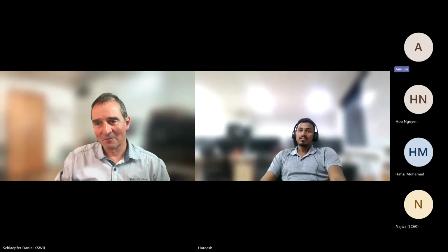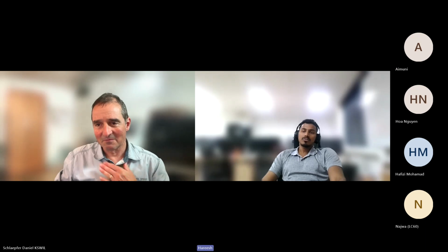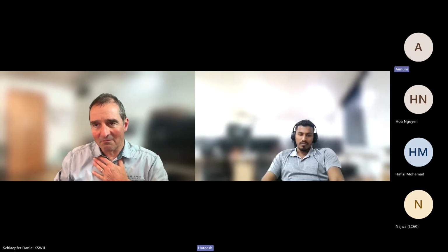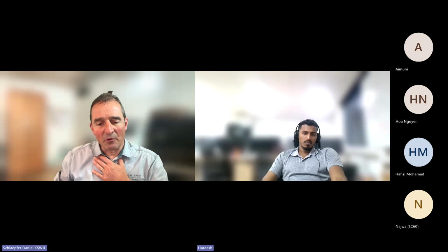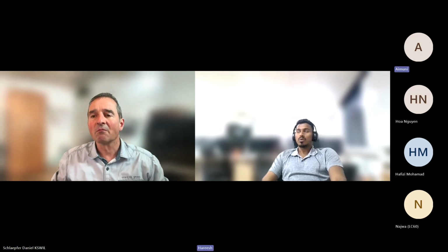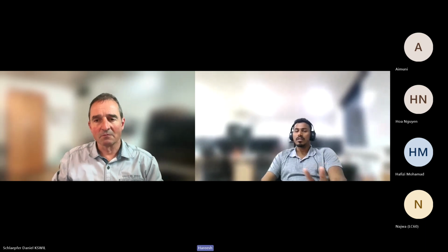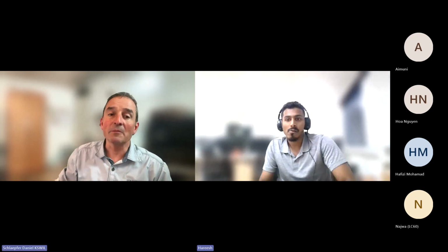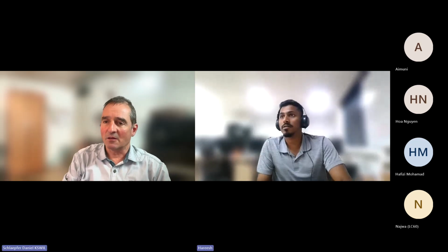All right. Just wanted your clarification on that. Do we still need to do atmospheric correction if we are using band 11 around 1.6? Because there's not much water vapor interference in there. Yeah. If you use a standard value of water vapor, then it doesn't help, because then everything is corrected the same and you will still have the variability. So you can use the same correction from Sentinel, and this will remove the water vapor based on the image. So for band 12, it's recommended to do atmospheric correction, but for band 11, it's not really. All right, sure. Okay.